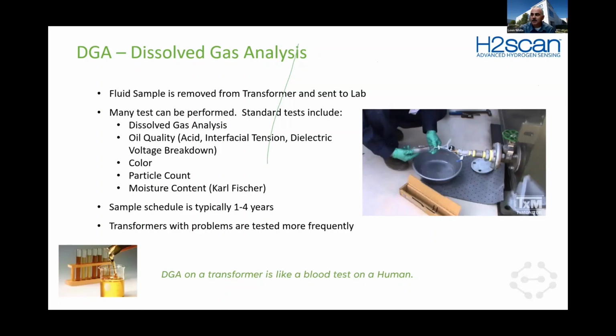We found that outside of substations, people aren't monitoring their transformers at all, or taking oil samples. So when we talk about taking oil samples, we're typically talking about distribution and transmission substation transformers.